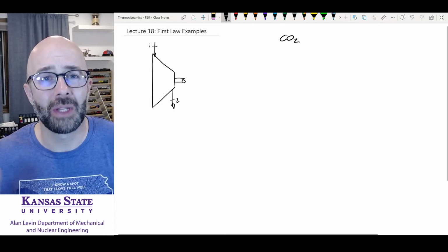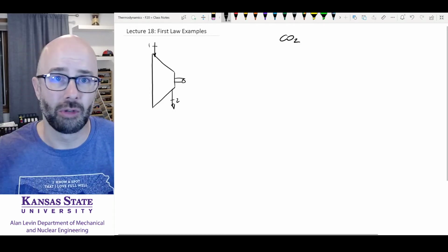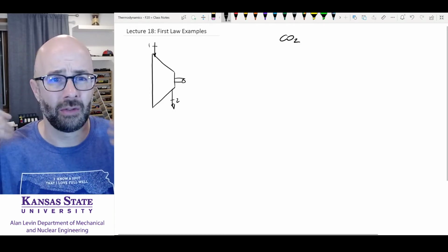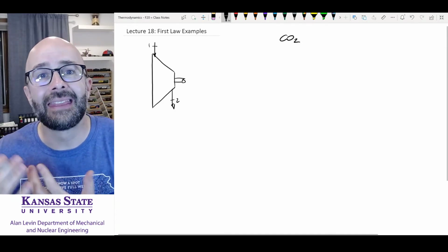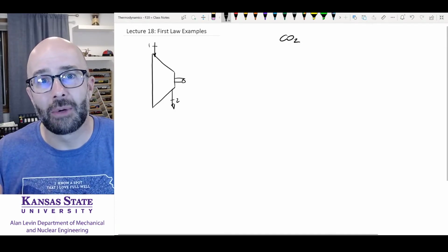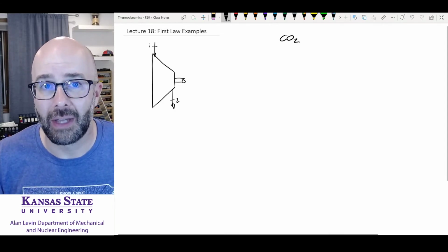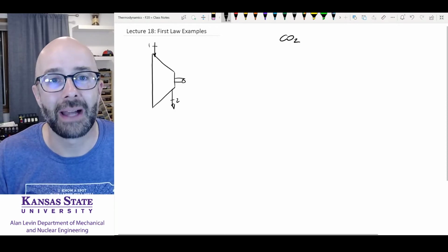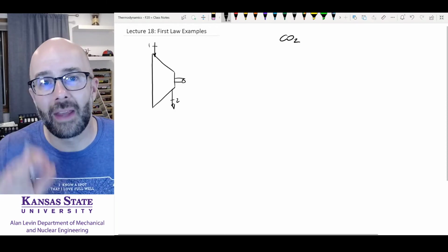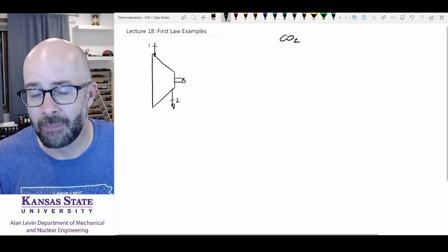But right now in the room that you're in, there is dry air and there is water vapor in the room. You've evaporated, you sweated, there's just all sorts of humidity in the air. At that level, when water vapor is not 100% of the air, it is going to act like an ideal gas when something called its partial pressure is low. And maybe go back to chemistry. So that's why that water vapor shows up in that table, in table A23.